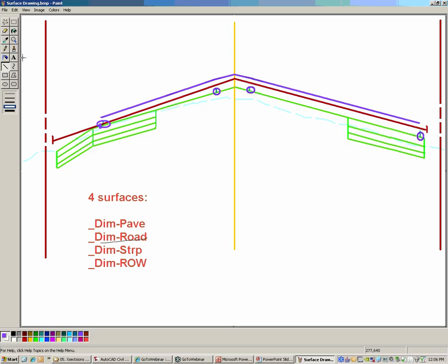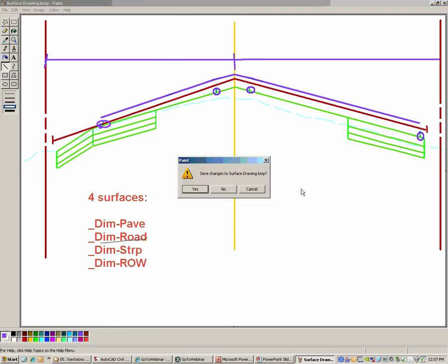And then last, the right-of-way surface, which is going to be a single straight surface that just comes right across, and it will label dimensions. Then it will label from here to here. So hopefully that gives you some sort of insight. We're going to have these surfaces that we generate on top of each other from the corridor model. It's really all there. It's just picking the right boxes, and using those surfaces, we're going to have the cross-sections label themselves. So let's get into Civil 3D here and do that.